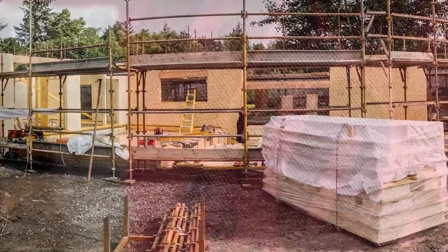The basic function of a breather membrane is to keep the timber in the structure dry during transportation to site, and until the final weather protection layers of the building are added. This not only reduces the moisture loads on the building, but helps ensure effective drying can take place later on. This can be thought of like a Gore-Tex jacket for the building. It keeps the rain out while allowing vapour from the building to escape and dry out. Our Frameshield membrane fulfills this purpose and has been used in timber frame for over 30 years.